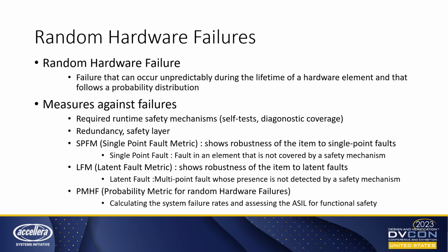For that, the single point fault metric SPFM and latent fault metric LFM were introduced in ISO 26262, and each ASIL level, automotive safety integrity level, requires a threshold for these metrics.